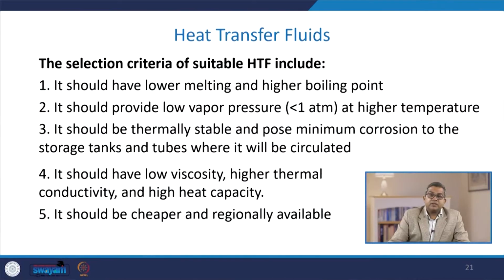Now there is a broad spectrum of selection criteria. The question arises that we are having a wide galaxy of heat transfer fluids, then how can we select the appropriate heat transfer fluid? One criterion is that it should have a lower melting and a higher boiling point. It should provide low vapor pressure, sometimes less than 1 atmosphere at higher temperature. It should be thermally stable and pose minimum corrosion to the storage tank and tubes where it will be circulated.